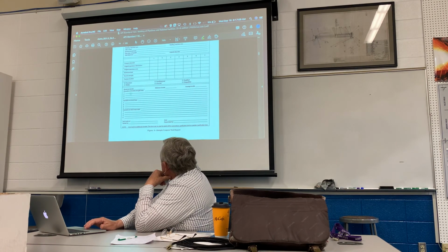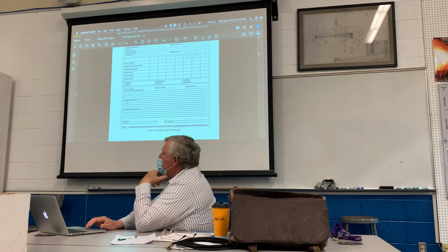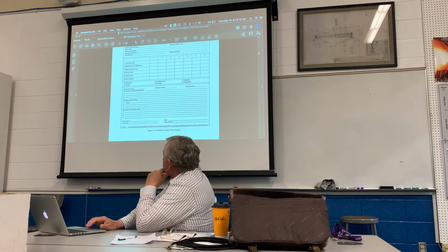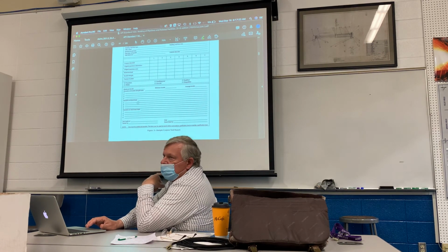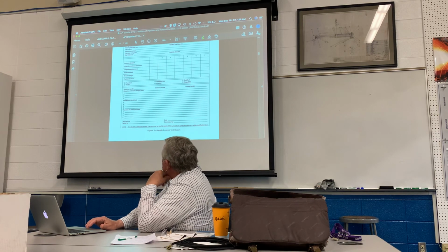You know, on the bend test you might put small porosity less than 1/32 of an inch. You can put that on there, or not. If he passes, he passes. But you can put any remarks that you want here. The test was made by, or test was made at, this is the location where it was made, company. Tested by, that would be you, the date, and then your supervisor is going to sign off on it here after he checks your data.